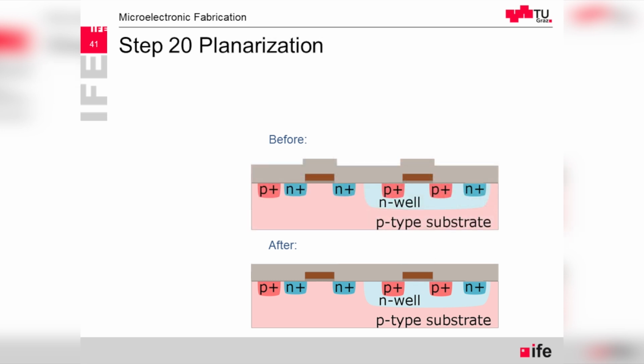And what happens already here, what we can see is that if we don't do anything, we would not have even structure, because in the chemical vapor deposition, we deposit equal thickness all over the wafer, but where there is the gate, there is a bump. And then every time we deposit metal layers, there would be more bumps at different places, and we would get problem of not being able to control the mechanical stability of the structure.